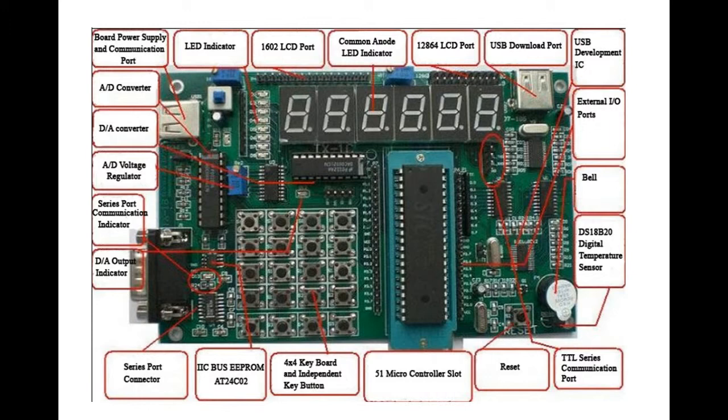Based on the output of the barcode scanner, the serial port transmits that information back to the microcontroller, and then the microcontroller can do the relevant internal logic and give me the output. So that's the communication purpose of this serial port.